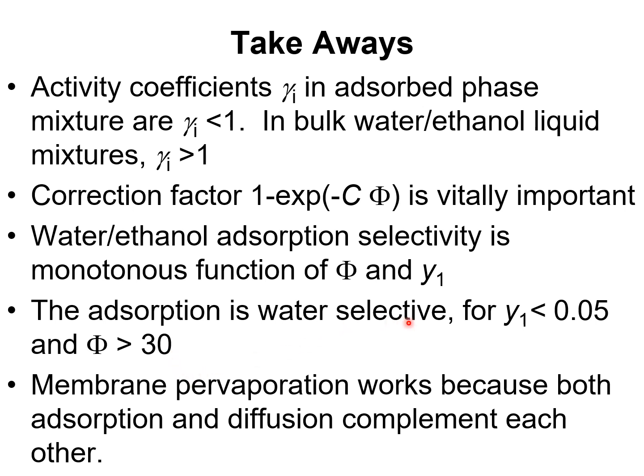This is an important aspect of membrane pervaporation, because for removal of water selectively from water ethanol mixtures with small amounts of water, the adsorption selectivity is in favor of water.